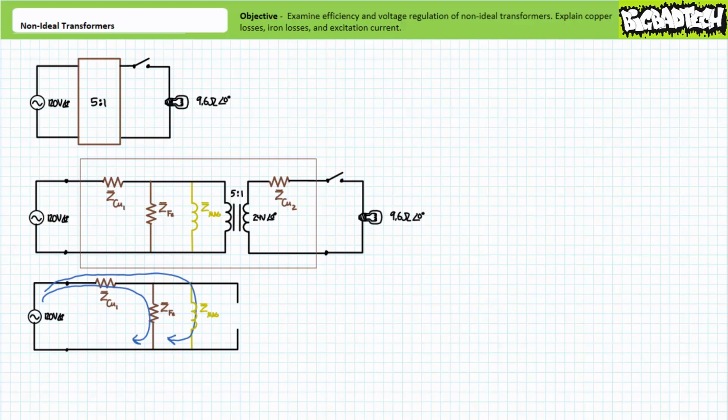Even when the transformer isn't powering a load on the secondary, the primary continually draws current. Importantly, note any current drawn by these leakage paths must also travel through the primary winding, and as such, the more current drawn, the more power will be dissipated by the resistance of the primary windings. Higher quality, extremely efficient transformers have large magnitude leakage paths, and as such, draw less current and waste less power in the standby mode.